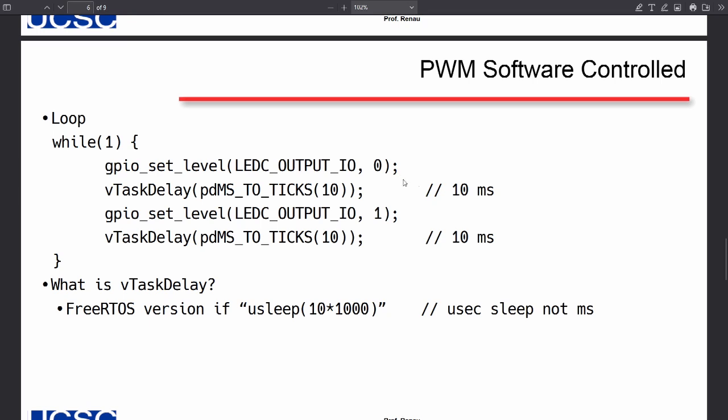What is now the period of this oscillation? Yeah, the period is 20 milliseconds. We take the amount of time that it takes to run, which is about 20 milliseconds. Then how do we convert 20 milliseconds into frequency? It'd be 1 over 20 milliseconds, which I believe is 50 hertz. Is that right? Okay, so this would be a 50 hertz oscillation at 50% duty cycle.